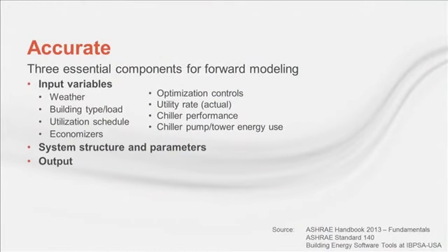Well-known modeling tools include DOE's EnergyPlus software, DOE-2, Trane TRACE, aka Trane Air Conditioning Economics, and Carrier's HAP. For a complete energy software tools directory, you can refer to the Building Energy Software Tools website hosted by the International Building Performance Simulation Association, IBPSA-USA. The best resource in terms of accurate energy modeling is Chapter 19 of the ASHRAE Handbook 2013 Fundamentals. It provides comprehensive information for various energy estimating and modeling methods.